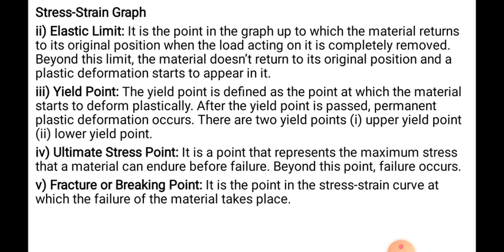There will be some deformation in the rubber band, and you are removing that external force, the deformation is also removed, and it comes to the original point. Now you are applying some excess force than the force applied previously. Then there will be some excess deformation in the rubber band, and it will not be regained to its original point.